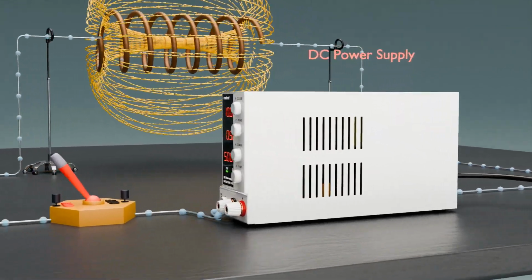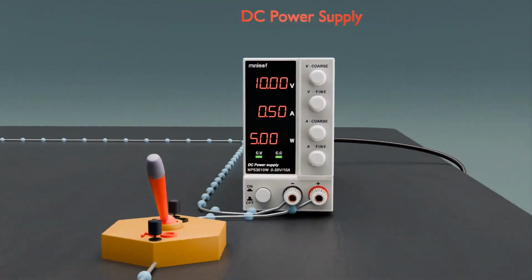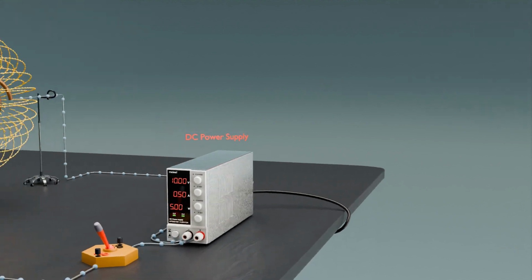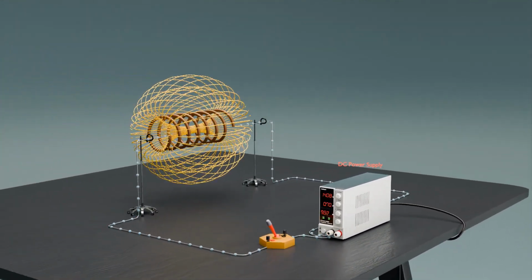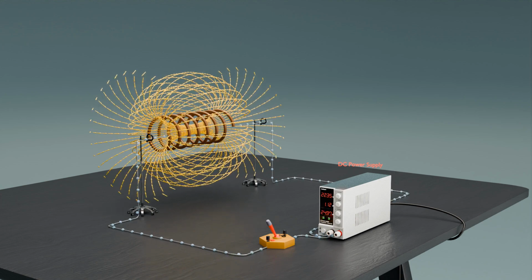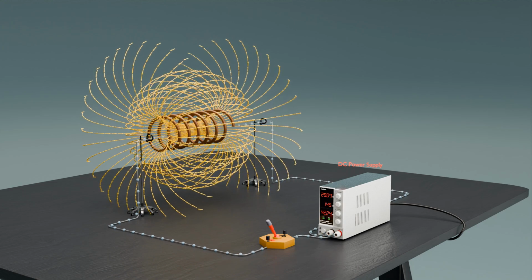We see a DC voltage source connected to an inductor. As the voltage from the DC source increases, it causes a corresponding increase in the current flowing through the inductor. According to Faraday's law of electromagnetic induction, the increasing current generates a time-varying magnetic flux within the inductor. This changing magnetic flux is proportional to the current flowing through the coil.